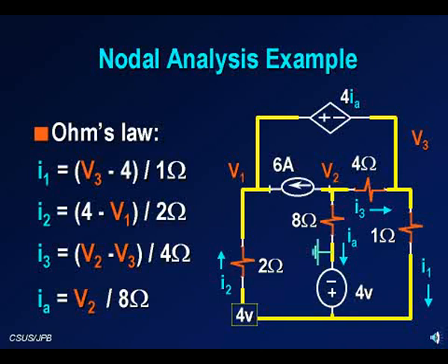Every time we write Ohm's law equations, the passive sign convention should be in our mind. It should be recalled. For example, we chose the direction of I2 arbitrarily because when we started the problem, we didn't know where current flows. We have no idea what the values of current or voltages are. So we picked those directions of the currents totally arbitrarily, and that's fine. So we selected I2 going from bottom to top.